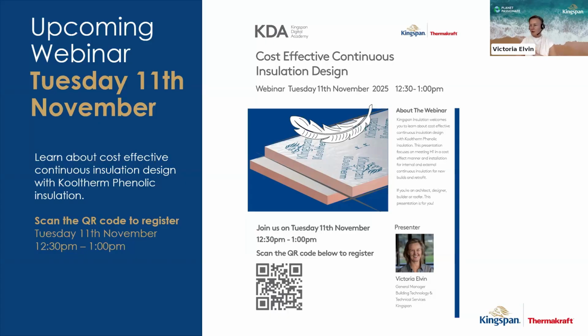To give you an example, I think a tapered insulation generally sits about 32, 35 kilos per meter cubed in terms of weight, whereas if you were looking to add screed, maybe not over a DD400, a screed sits around 2 tons sometimes per meter cubed. So the weight consideration is huge for tapered and one of the distinct advantages.